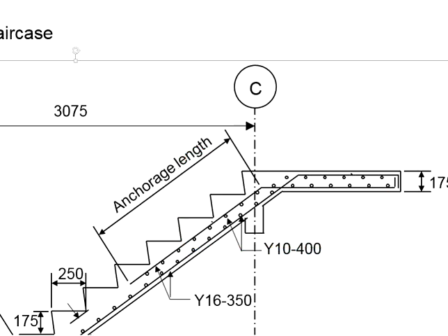However, such an arrangement of the reinforcement bars has a problem. This is where the reinforcement bars meet. Ultimately, without strengthening by other reinforcement, a hinge can occur here.